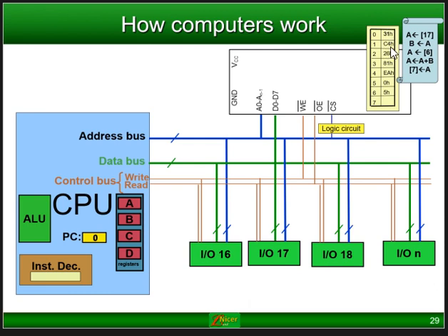The next one, C4, for this specific example, again, as I've said, don't bother about what it says inside here. The point is there's an instruction. This instruction C4 means in this case, take the contents of A, and place it in register B. So go from here and place it there. It's actually a copy. So if you put a value in here of 9, and you say put it in B also, it will copy the contents, meaning it will remain in A and also move to B.